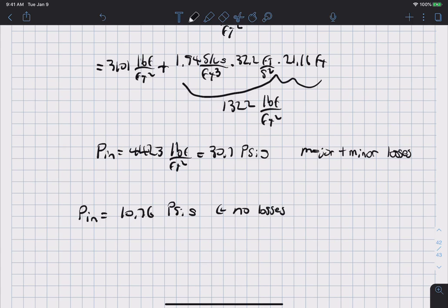However, if you include the viscous losses, you get 21.5 psi gauge pressure, and that's only the wall friction, from the wall shear stress as the fluid flows through the pipe only. And if you add the fluid friction as the flow gets turned and goes through all the components, which are the minor losses, you get 30.7 psi gauge pressure. So that's major plus minor losses.